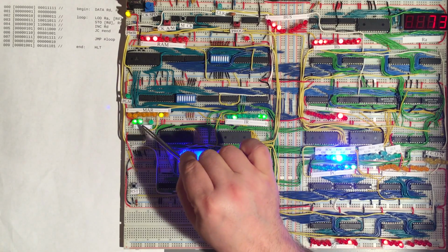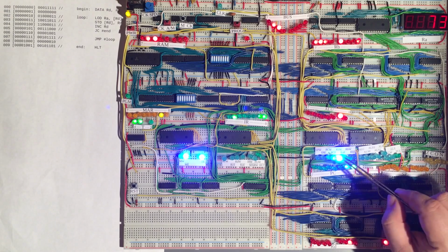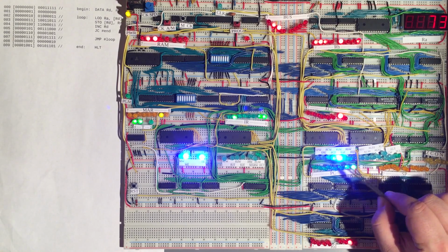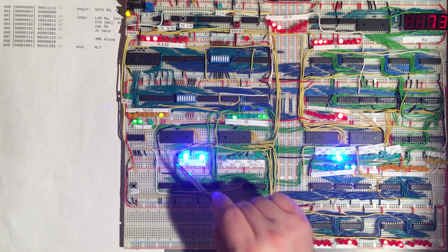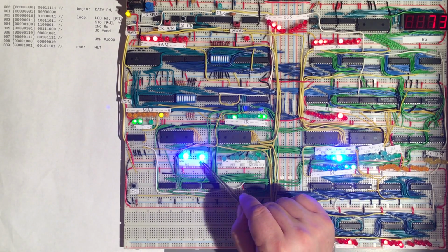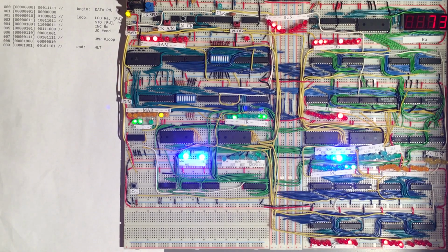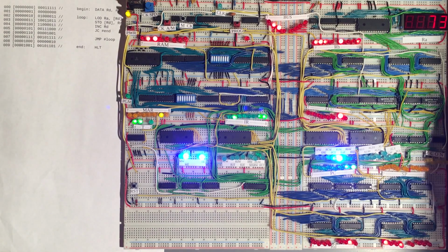And so the microcode for time t3 for this load instruction is a memory enable and then a write signal for whatever register we want to write to. And since this is the last microcode piece for this instruction, we are also asserting the timer reset signal. And so that will complete this load instruction. So this value, which is this here, will get loaded into the A register. So that's a load instruction.